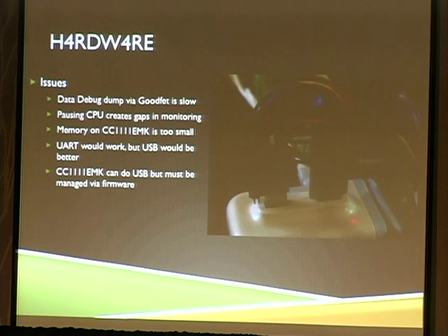So if I want more memory on the board, we're going to have to build a new board. Getting data off, we could do it via UART. I was working on that, but we got to the point where Atlas came free, and he started developing a USB library. The CC1111 chip has USB capabilities, but it doesn't have it by default. It's not built into it. You have to implement it within the library, so you have to tell it how to communicate with USB.